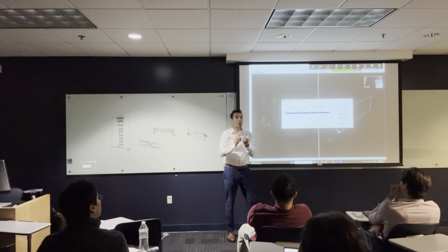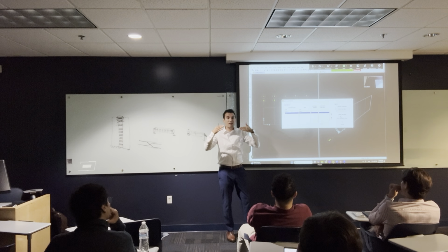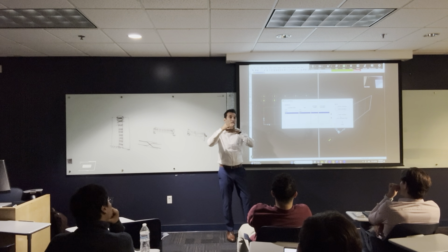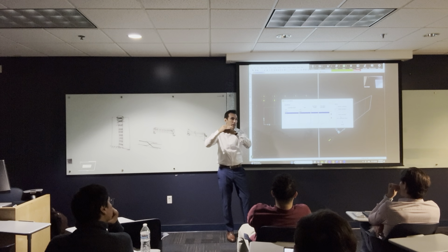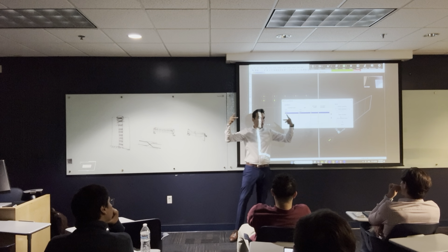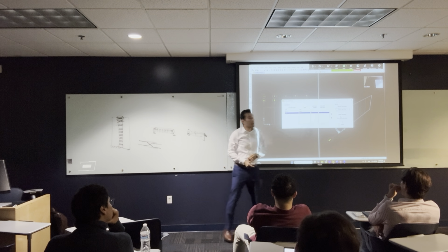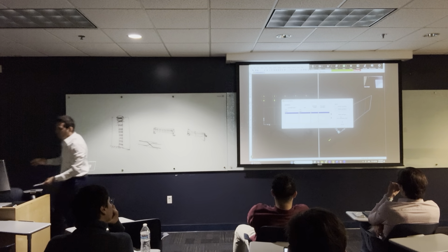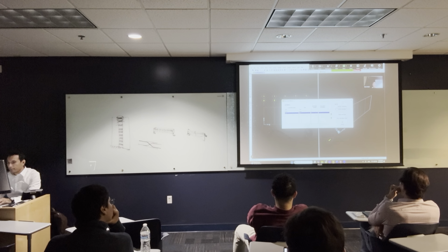By the way, SAP 2000 only runs case by case. It cannot combine the cases unless you tell it to combine cases. So SAP 2000 is going to run the dead load separately from the live load, and it's going to calculate the own weight. Okay? So I'm going to keep it 0, and I'm going to modify.